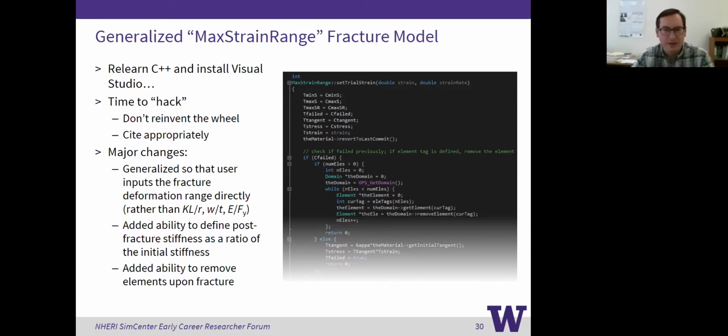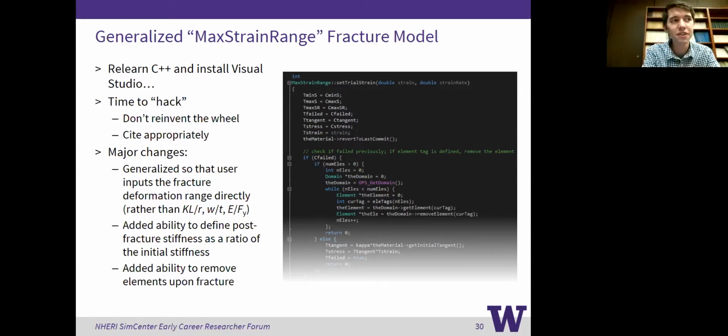Regarding the initial imperfection that you're adding for the brace, is that a constant value or does it vary by time? The initial imperfection is seeded in the brace, so it's the actual node locations that you provide. And what's typically done is to use 1/500 times the length of the brace. That's pretty close to the limits for imperfection in the steel manual, and so it approximates the buckling equation pretty well also.